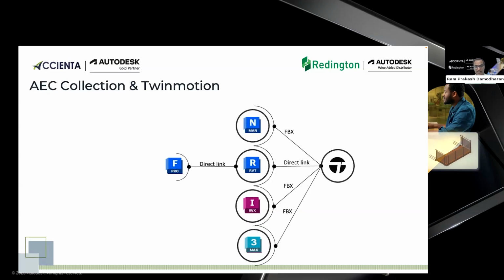Navisworks Manage, yes. You have the federated BIM model, which is done from Revit, and you are viewing all the clash detections, and you want to make sure the federated model can be shown as a beautiful, realistic visual to satisfy the client's needs as per the design thought. You take the model into Navisworks Manage, export it as FBX format, and link it to Twinmotion as well. And it's not limited to that. We still have a few more.